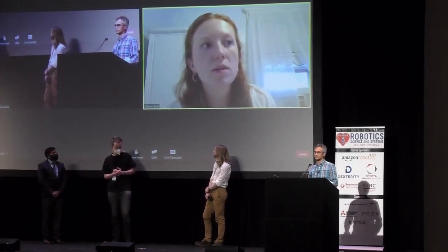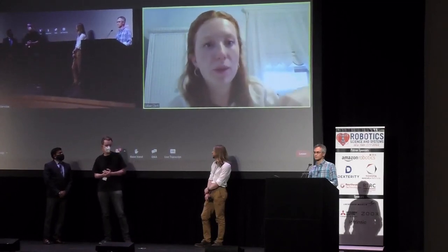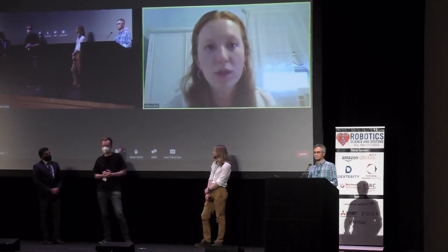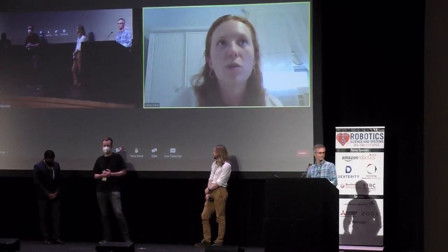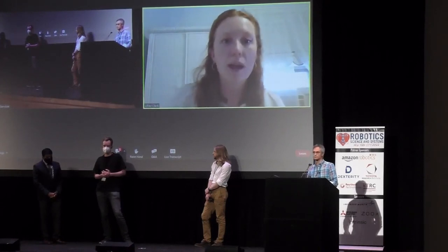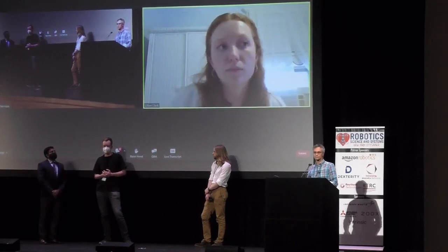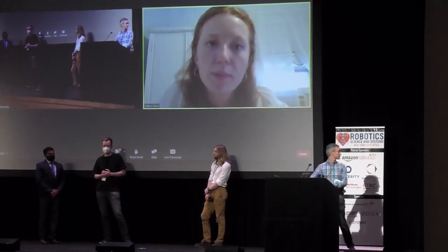Yeah, that's another good question. We mostly were looking at this for specific applications in which the robot's trying to make decisions about where to return to in the environment where they would have good signal strength. So raw SNR was the only metric that we were really interested in, and that was the main application that we considered. If you wanted to get more broader system level metrics, it would be good to look at things like how much data actually flowed over those links, latency. There are other things that we could consider, but that's what we focused on for this work. Thanks.